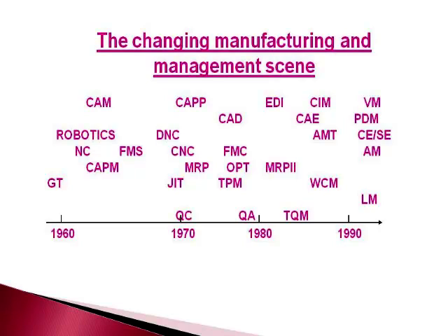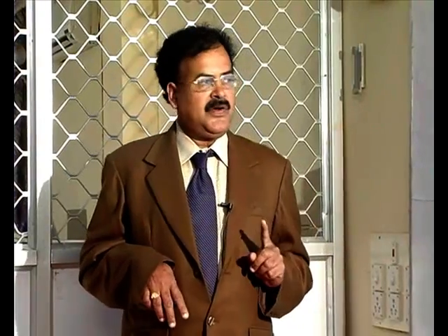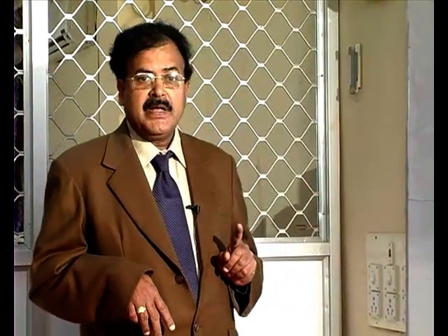See, previously in 1960, we thought of group technology, and from 60 to 70 in production systems, applications of robots, applications of NC, and applications of some FMS and computer aided manufacturing. These kinds of things came between 1960 and the 70s. In the 70s itself, the direct numerical control concept, previously developed, was implemented successfully. So we can control several sets of NC machines by means of one supervisory control, that is called a DNC computer. Like that, and the JIT concept also evolved in Tokyo.